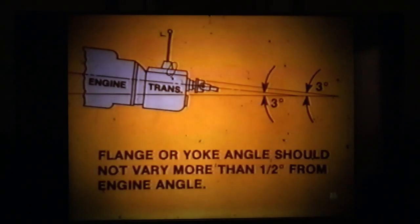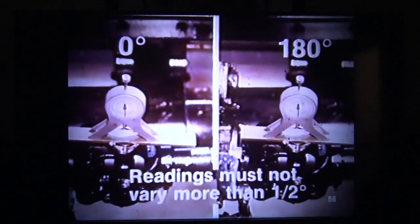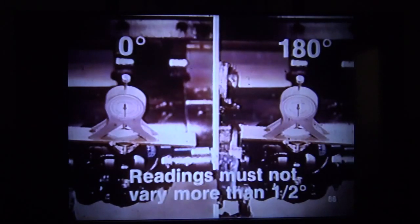In either application, the results should not differ more than 1/2 degree from the engine angle. If it does, it suggests that the yoke or flange is distorted or the engine and transmission are misaligned. Flange or yoke distortion can be determined by rotating the flange or yoke 180 degrees and taking a reading with a protractor. If the reading varies more than 1/2 degree from the previous reading, the flange or yoke is defective